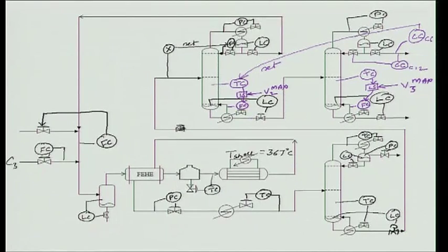What about this chap, the temperature controller on the third column? Well, again I cannot afford this temperature control to be lost, because if it is lost, then too much cumene will leak out the bottoms, and cumene is precious, that represents a significant economic loss. So, now how do I manage it? I say that, well, in order to keep V2 at max, because that is what I want to do, now I am putting the optimal constraint controllers. Since V2 is to be max all the time or close to max all the time, I put a supervisory controller that takes the boil up,